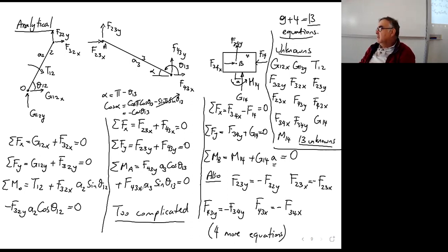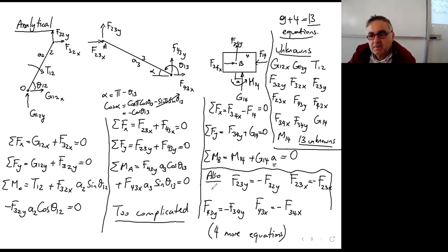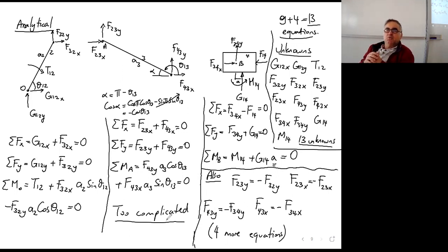For example, you don't really need to use these 4 compatibility equations, you can directly implement them. And using the fact that some members are two-force members, some are two-force and a moment member, and some are three-force members, you can simplify your equations and get a solution very quickly.